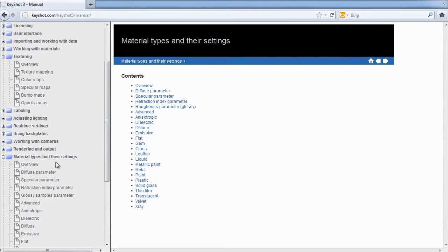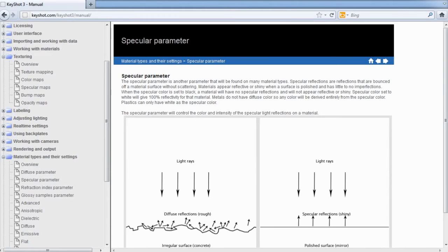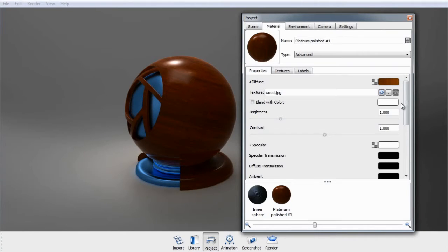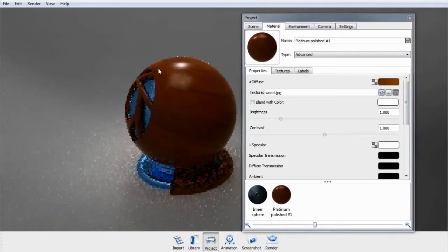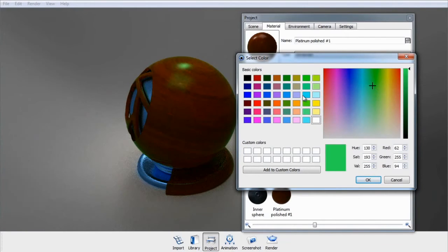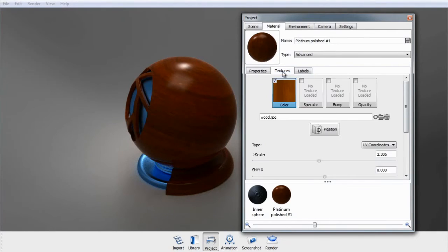So, for example, if you look at my highlight here, if I go to the specular color and set that to green, notice my reflected color is green. And if I go all the way to black, I have no reflective color. And the reason I'm showing you that is because those can be mapped using textures. So what we're going to do is create a painted metal texture. I'll go back to the original texture that I was using, and that's that painted metal color. And this is a PNG with transparency.